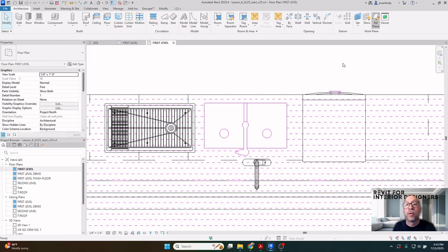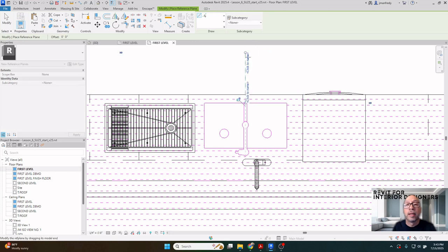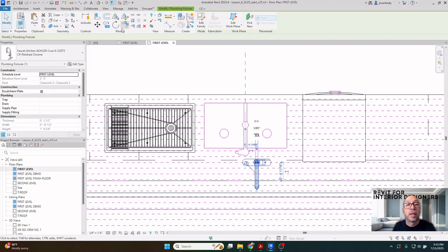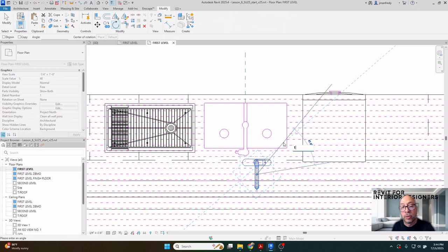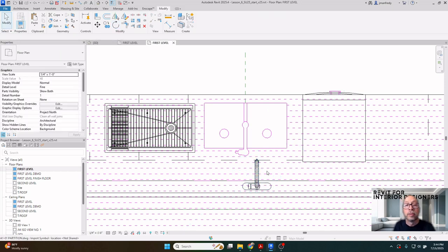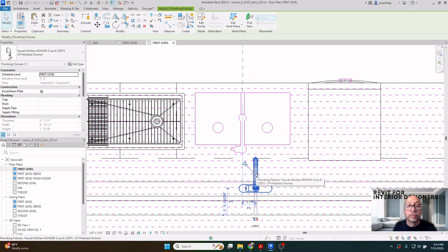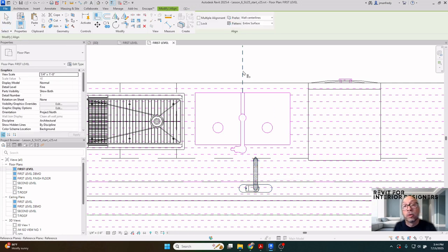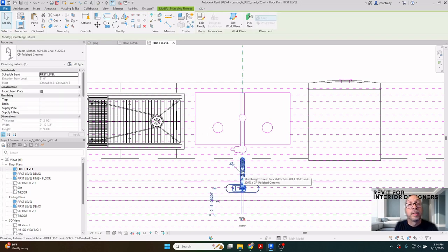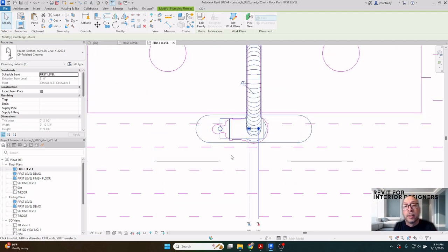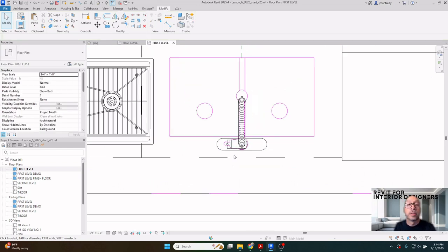And so I'm going to grab a reference plane and drag a line there. I'm going to rotate this object here with the rotate command. I will simply choose a point and choose 180 degrees. And then I can move it into position. I can type AL for align, go to the green line, choose the center of the object. And then here, I can simply use my keyboard, shift and arrow keys up and down, or use it without the shift. It's got a shorter range when it jumps. So here I can place it right there as an example.